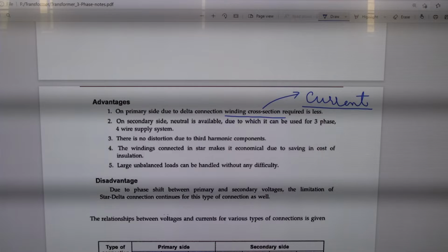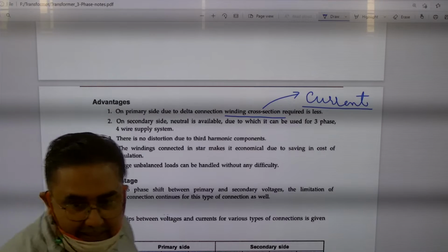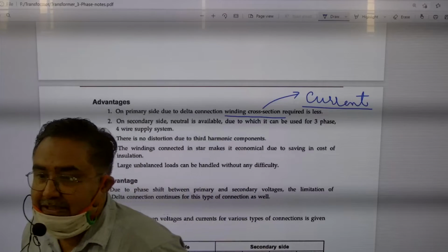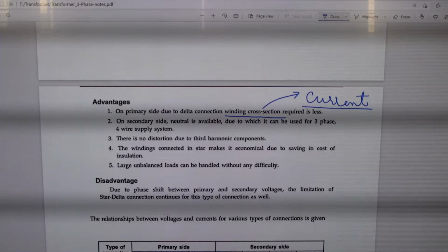But in general, since we have one type of wiring, for all fans and tube lights we go for 1.5 mm square. For geyser we go for 2.5 mm square, or for a refrigerator like this. And for AC we go for 4 mm square. And for the distribution board, which comes from the meter to your isolator, you go for 6 mm square.